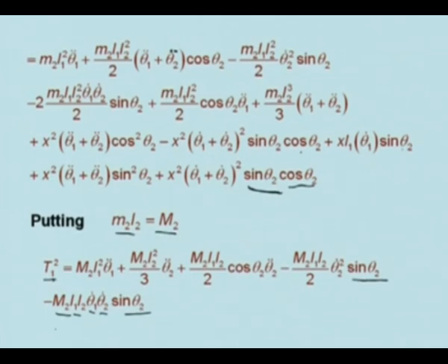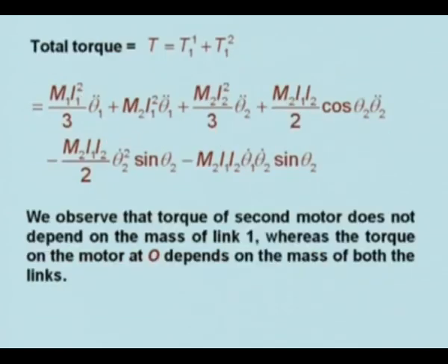If it was not so, if M1 was a function of x, like in a tapered rod, then we would have to put it inside, and in some cases we can integrate given M as a function of x, while in some cases we have to use numerical methods only. So that has to be done.